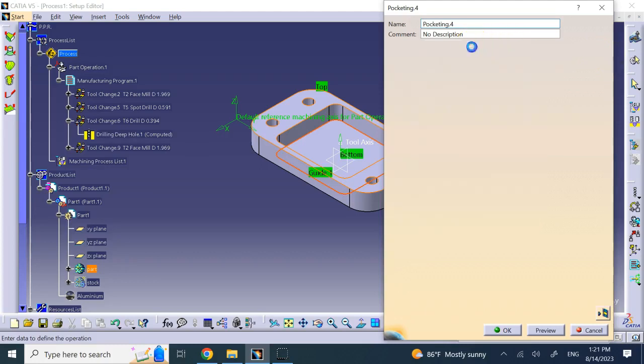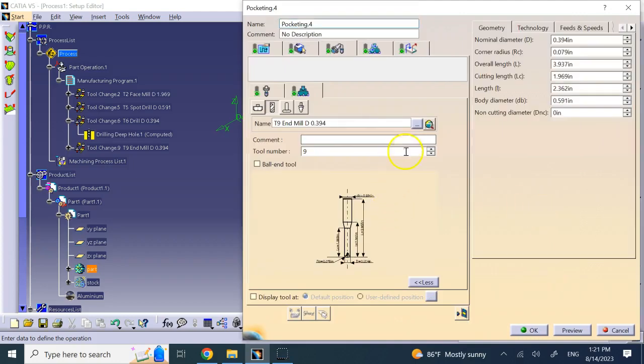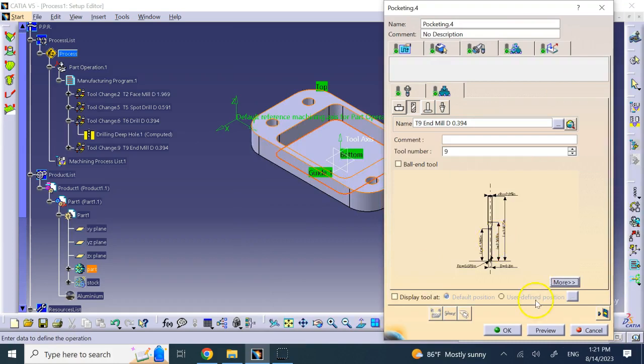And the next thing is you choose the end mill for this, and make sure that the end mill is small. Really, don't go with the big end mill. It has to be quite a bit smaller than this radius here, right? The diameter of it. And so for that reason, I choose my mill a little bit smaller in this case. And so I can get the geometry that I want.